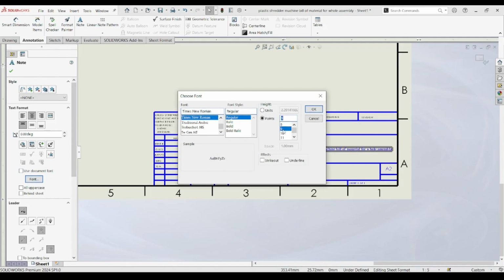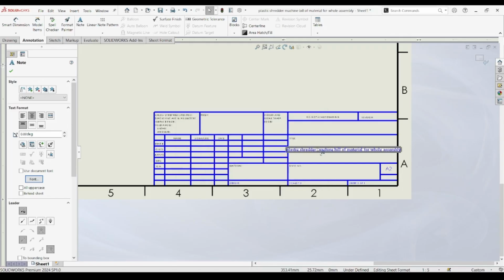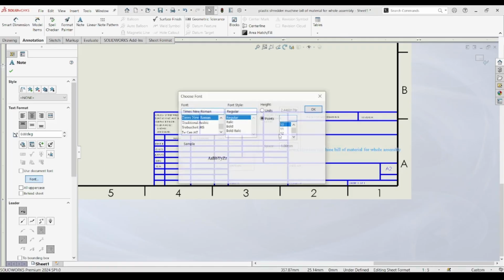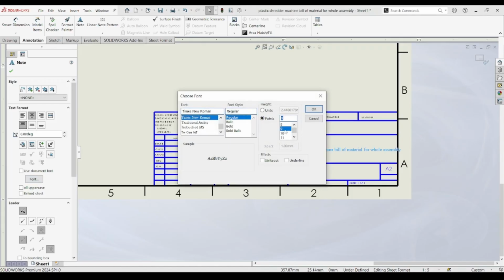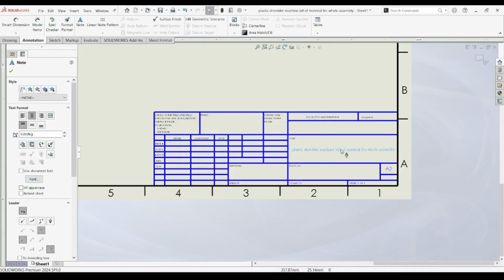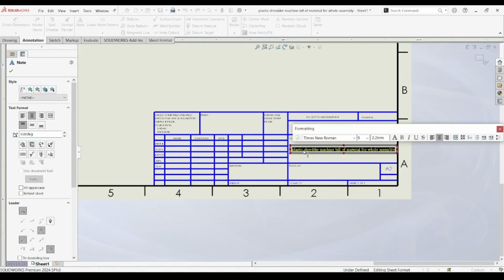Additionally, we demonstrate how to reorder items, adjust balloon callouts, and sync the BOM with the drawing views for clarity and ease of understanding. This step ensures that when your workshop receives the manufacturing drawings, every part number in the BOM matches the numbered balloons on the exploded view or orthographic drawings.